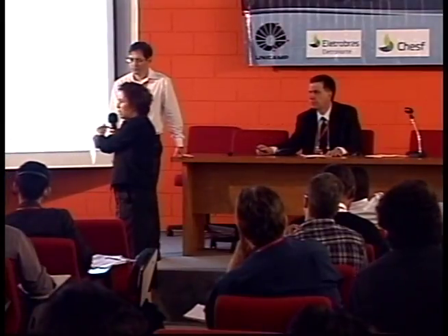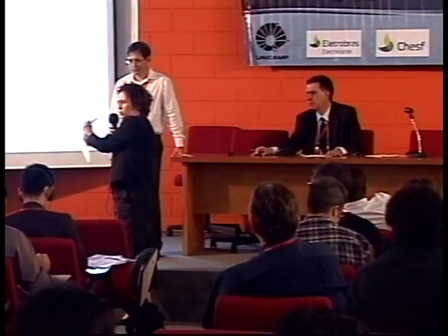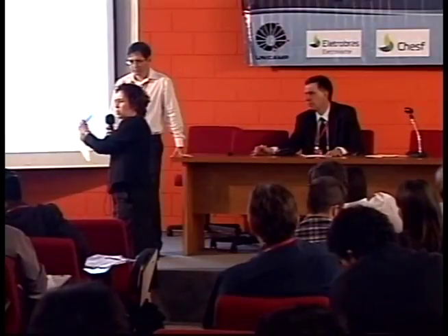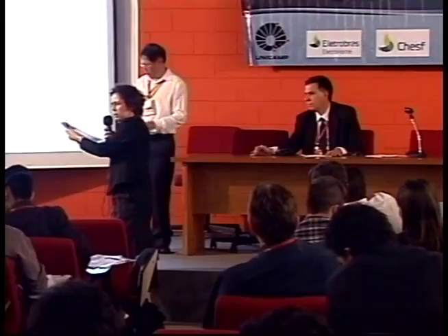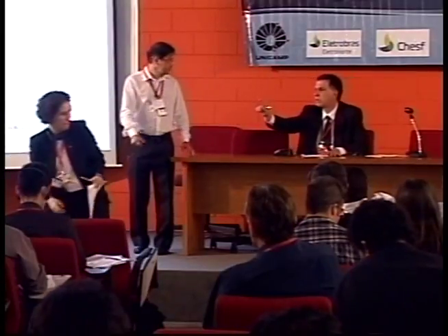And for the amount of energy, we know that the overvoltages will be really high. This is why of the mitigation method we are proposing, which is going to be presented in the TRT project tomorrow, because the energy is high. For a single-phase fault, which is the more likely one to happen, we have a problem with the energy of the surge arresters located at the end of the line. The energy is high, but as we're going to see with the protection tomorrow, the conventional protection today is already enough not to allow the overvoltage to become too high.